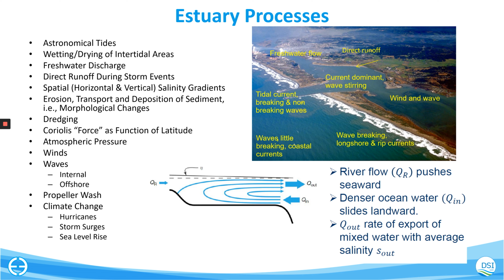If you have an estuary or a coastal floodplain that's got a lot of cells, say you know that this area maybe at high tide is all wet, you still want those model cells in your domain, but you know that you don't always need to be looking at them to see if they're wet or dry. So you can save some computational effort in that regard using the dry step setting in the hydrodynamics tab.